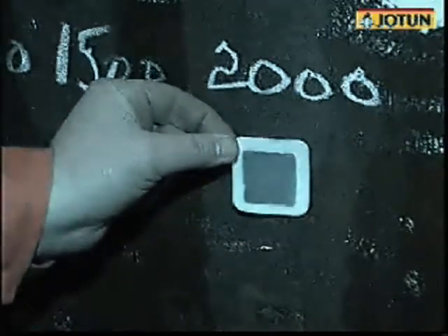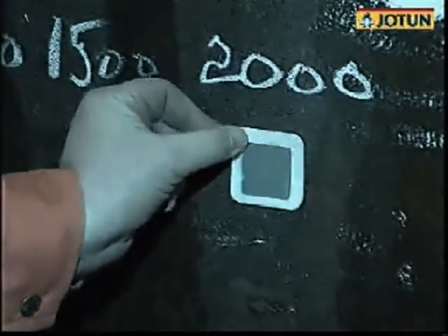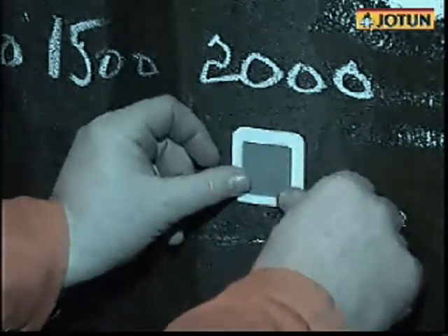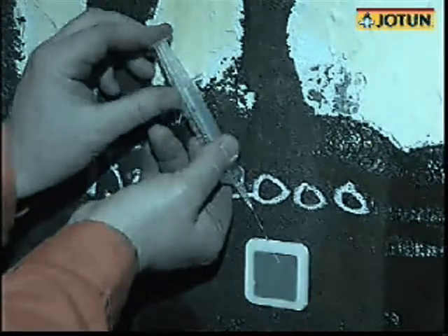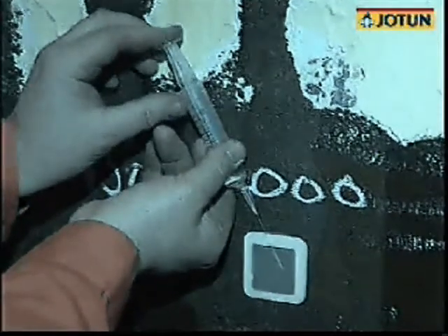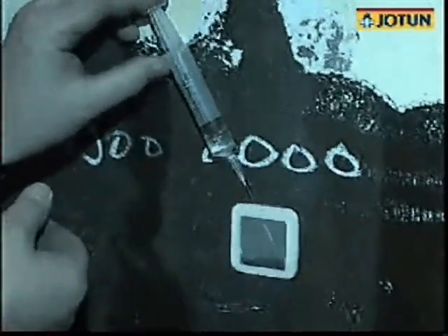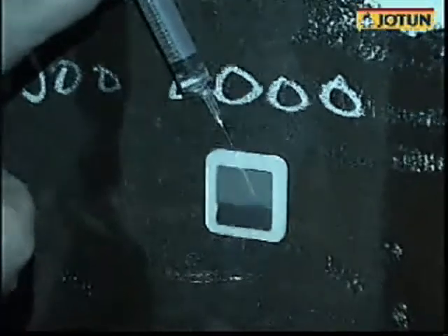In contrast to blast cleaning, water jetting removes water-soluble salts from the substrate. The removal of salt reduces the risk of osmotic blistering. The salt level is checked by the Bressler method.